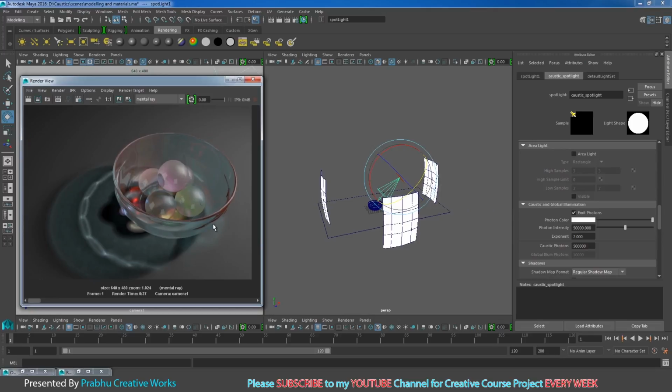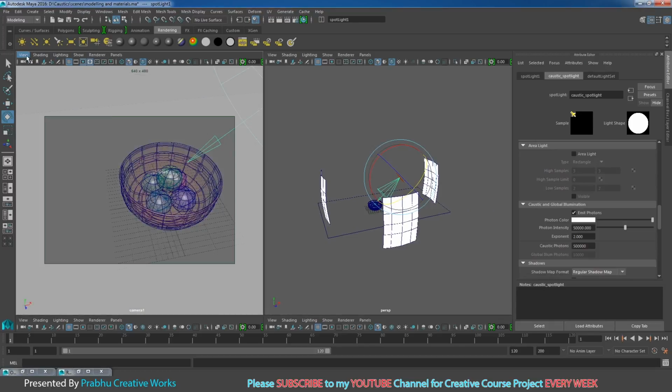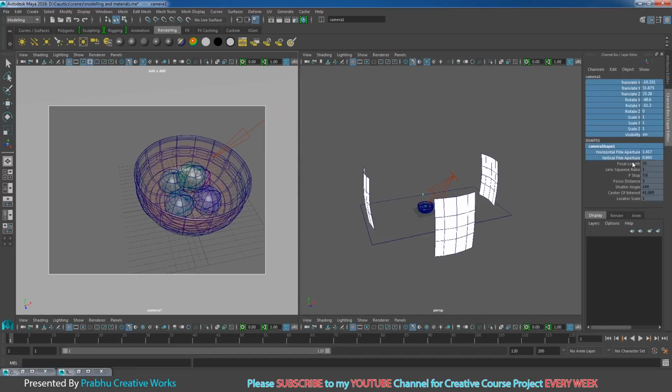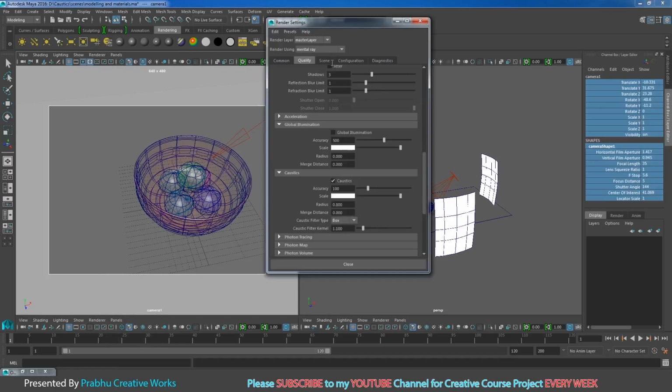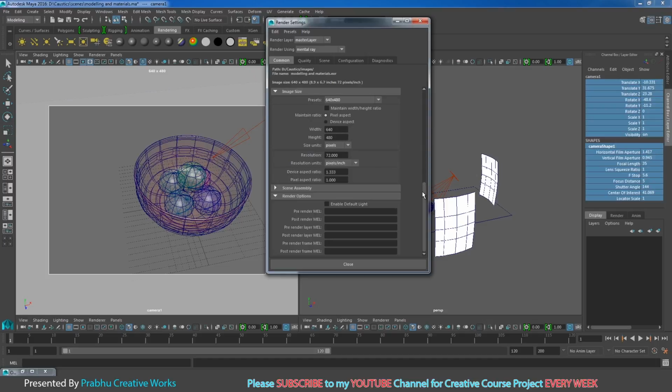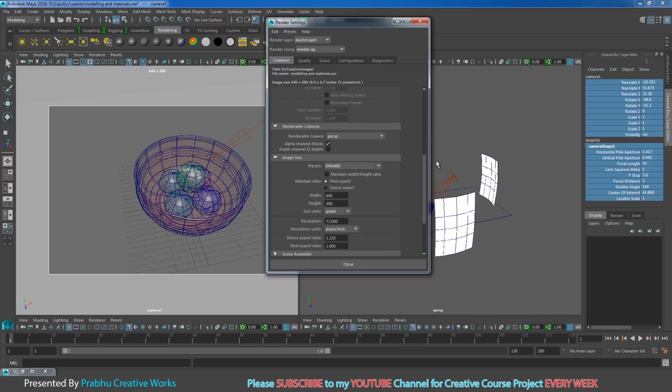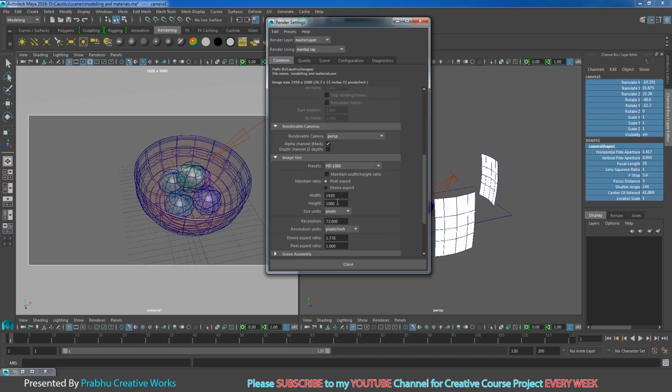So now we got the final render over here. Now we want to set the camera view. So go to view, select cam. I will unlock all the attributes. So I will select all the attributes, right click and choose unlock selected. Now go to render settings. In the common tab you want to increase your image size. So I will right click and choose HD 1080.